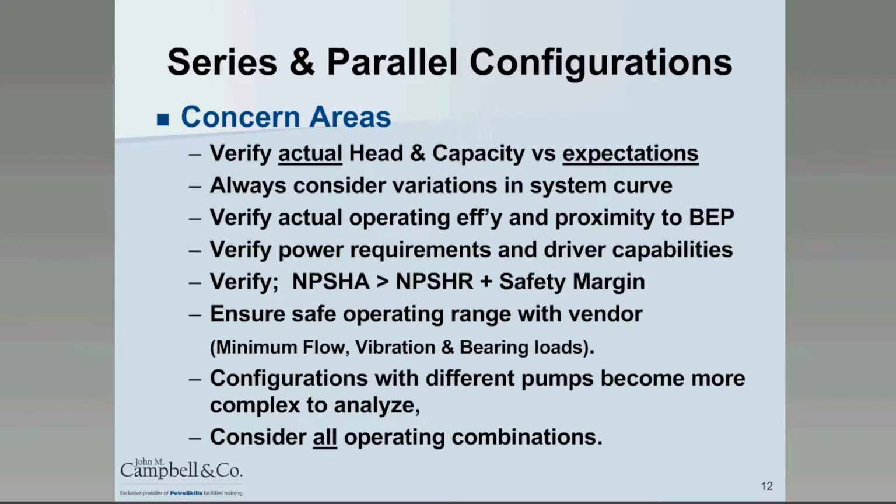The biggest challenge that you're going to have is establishing your system curve. And that system curve may be something that you develop through either calculation or field testing. So there's different ways to determine your system curve and find out a good way to plot that onto your pump curve. Always consider variations in your system curve. Thinking that life is static and doesn't change is a little falsity, and trying to understand the effect of control valves or changes in reservoir, injection reservoirs is very important.